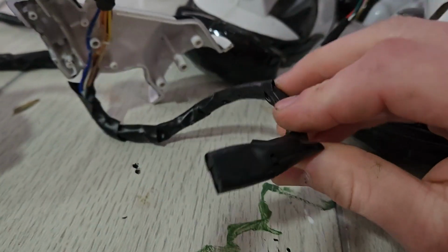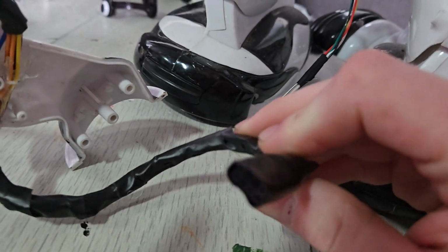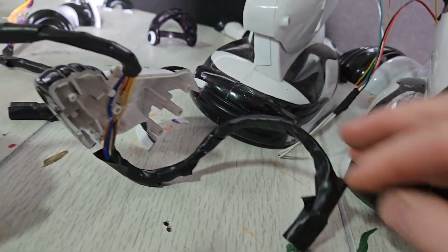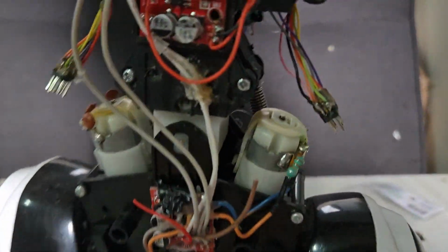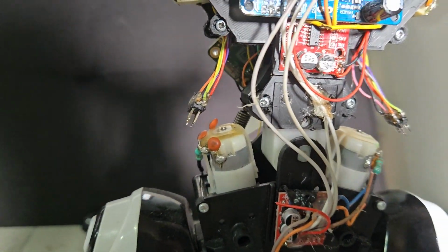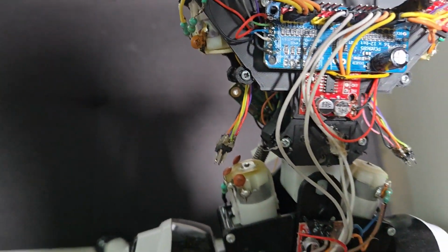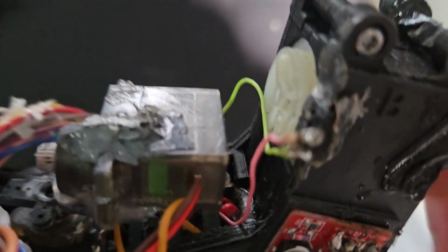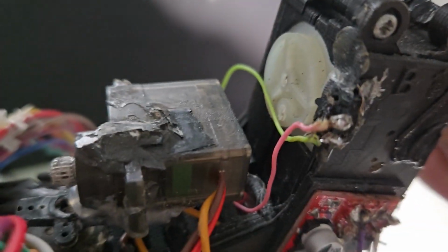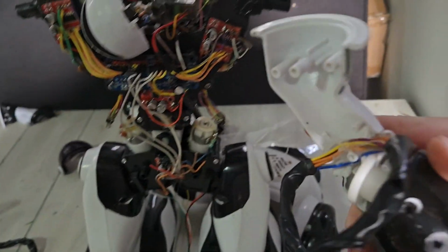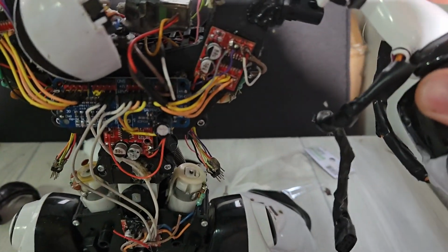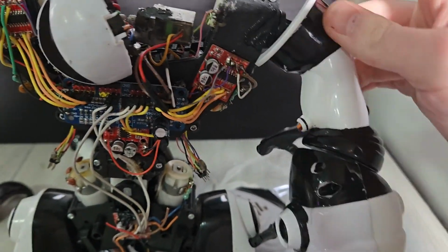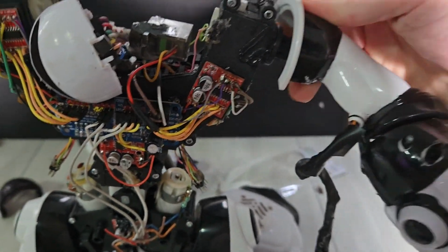And you remember those 8-pin arm connectors from earlier? You'll have to recreate that on this right here so that you can easily attach it to the robot. That's why I stressed so hard about the 8-pin arm connectors. It's a nightmare without them. So now all you have to do is line up the arms with the limit switches inside of the frame, like so, and then you'll grab your arm and then attach it, and it should look something like this if everything went right. There you go.